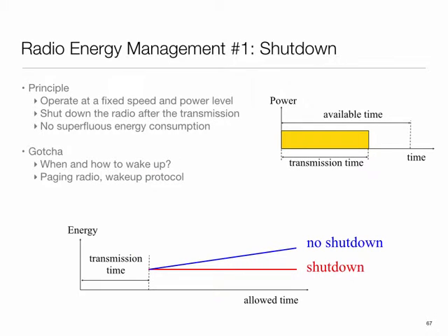In the case of Ethernet, we saw that while there was room for scaling, because 10 gig Ethernets were very power hungry, the way the standards worked out, scaling never happened. In the case of wireless, scaling does take place. In fact, your Wi-Fi radios all the time scale the rate. Some of it is because of maintaining link robustness, but some of it is also to minimize power consumption. So for radios, there are two broad schemes then.